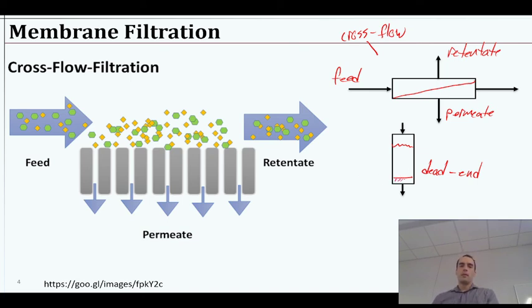Okay. And that would be the membrane. All right, so cross flow filtration then, we could illustrate it here where we have a membrane. You see these pores being the spaces where water can go through. And you see we've got this feed water, it's dirty, meets the membrane. Membrane's hopefully rejecting all these particles. And then this retentate is extra dirty with those particles, carrying them away from the membrane so it doesn't get fouled up as badly as it would have.